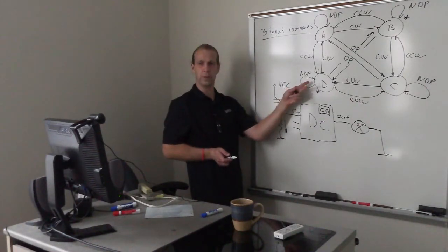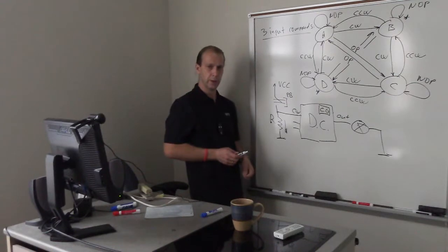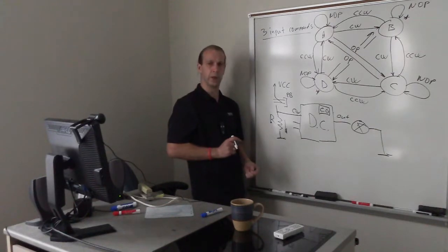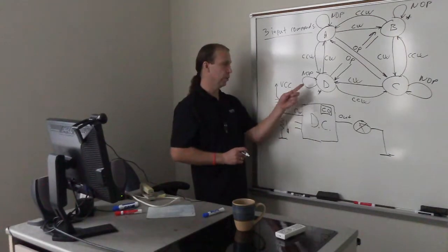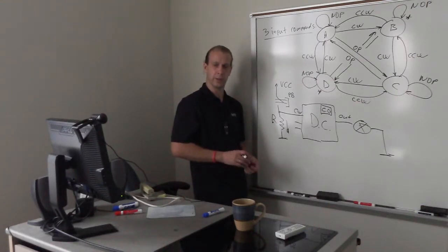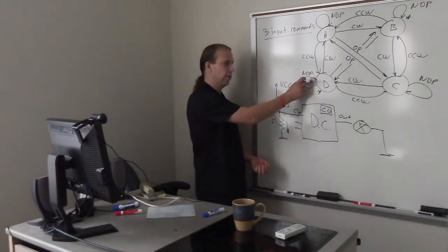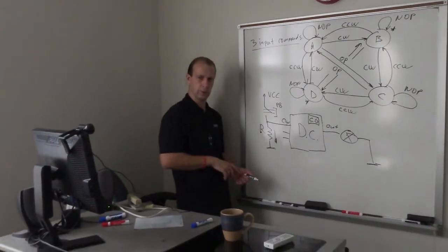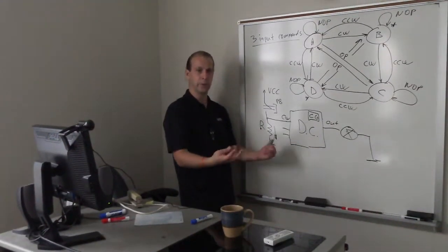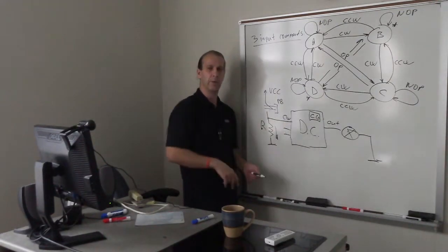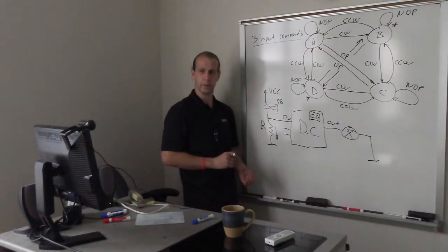And actually, this will be the main source of optimization of our circuit. Without no operation, our final logical expression for the excitation functions for triggers will be long enough. But with the presence of no operation, we can introduce don't care conditions. That's what you practiced with the second assignment. This is where don't care conditions come from. When we press more than one push button, it creates a don't care condition, because we do not change anything. We don't care if more than one push button has been pressed.